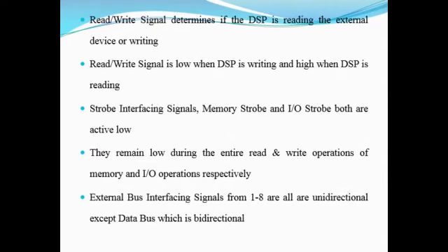Read or write signal determines if the DSP is reading the external device or writing into the external device. So if this read or write signal is low, then the DSP is writing, and if high, the DSP is reading. So that is what we have to consider.